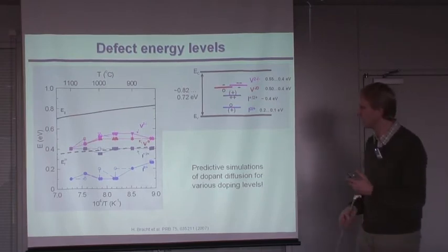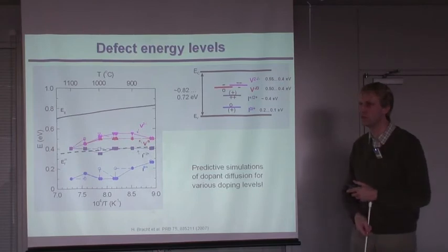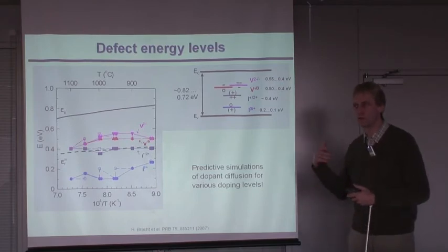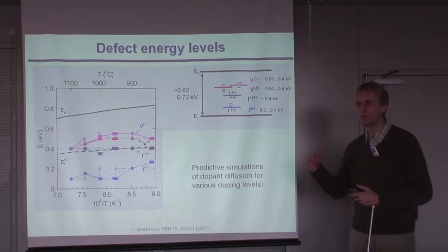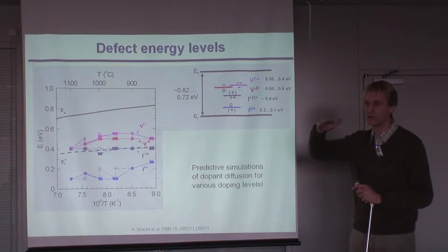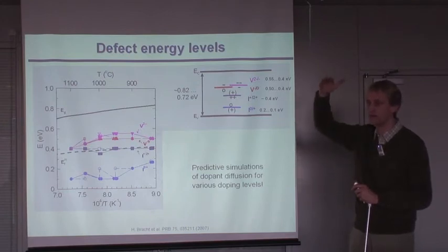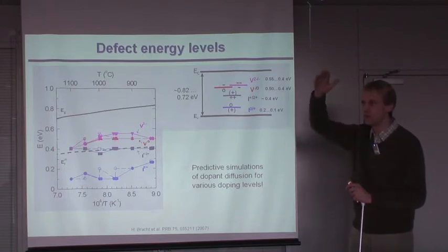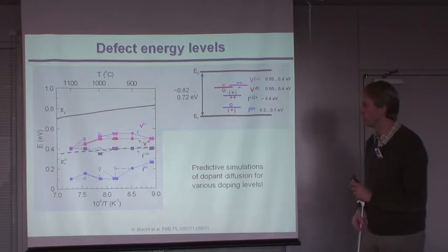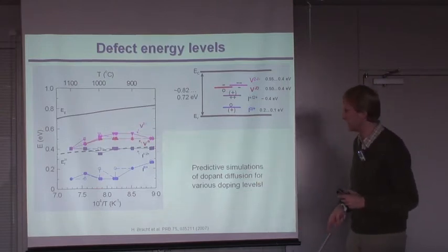profiles. So in order to get that out, you have not only to simulate boron and the corresponding silicon diffusion, but you have to simulate all simultaneously. Boron diffusion, silicon diffusion, arsenic diffusion, silicon diffusion, phosphorus diffusion, silicon diffusion at a certain temperature. Because by arsenic, phosphorus and boron, you move the Fermi level in the n-type doping to the conduction band, and in the case of p-type doping to the valence band. And so you need all these kinds of behavior in order to get that out precisely.